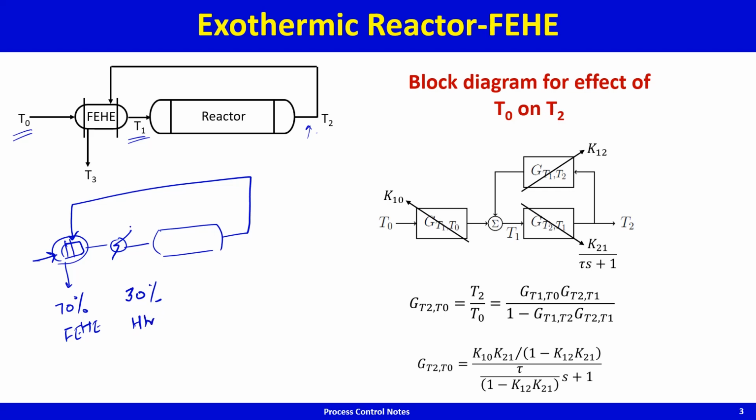And now what happens is, what is the heating duty? That's a controlled degree of freedom that you have introduced in the design of the process, and if you control the temperature, you see, because this temperature is now held constant, the buildup of temperature due to energy recycle is prevented by removing as much heat or adding lesser heat in the preheater, so that the temperature remains where it is supposed to remain.